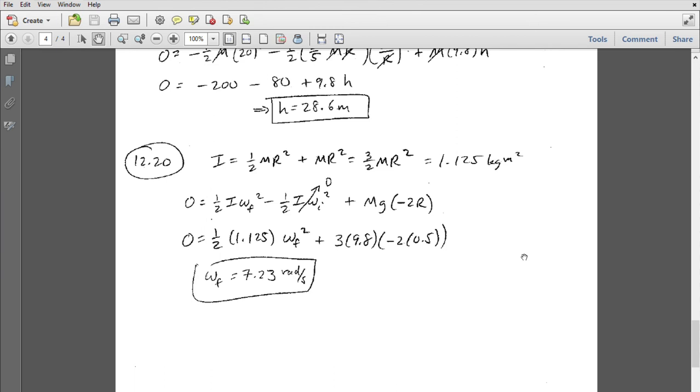So this is an energy methods problem because we know at the very top the angular acceleration is 0, and then it gets bigger and bigger and bigger when that mass is out to the side, horizontal from the rotation axis. The alpha is maximum, and then it gets smaller and smaller as it goes down to the bottom. So alpha is not constant. We can't use kinematics to solve this because it's not a constant angular acceleration kind of motion.